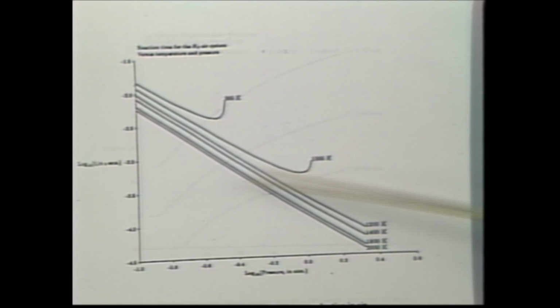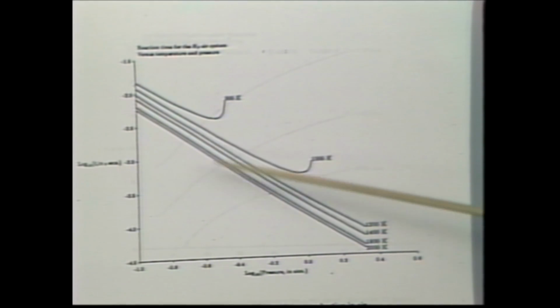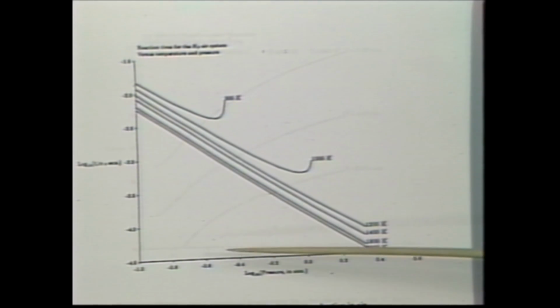And you see several lines plotted as a function not only of temperature, but also as a function of pressure. Several key things to note. One, as I up the pressure, the time required for combustion drops dramatically. Two, notice that increasing the temperature also tends to drop the time required for combustion. Third thing to notice, we talked about a reasonable combustion time required for a scramjet. Generally, we can guess that we've got to get that fuel to burn in at least about a millisecond, or thereabouts. Well, the millisecond line is right here, and I'll indicate that with the pointer.